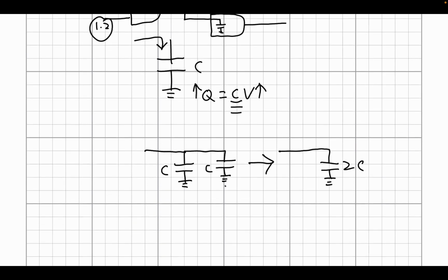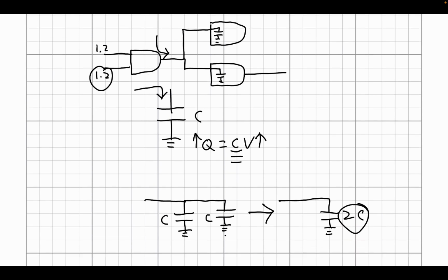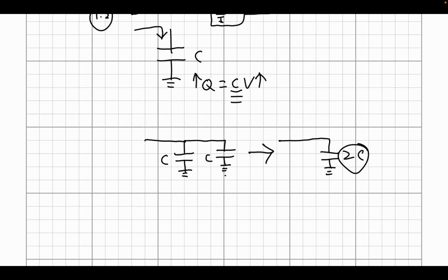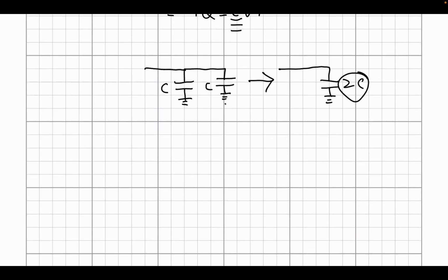And this is the problem, because by using two different AND gates, what we've basically done is we've doubled the capacitance that we have to charge up in order for our output to change. And so by connecting two logic gates here to this logic gate, we've basically made it so that the first logic gate is twice as slow. And this is Fanout.